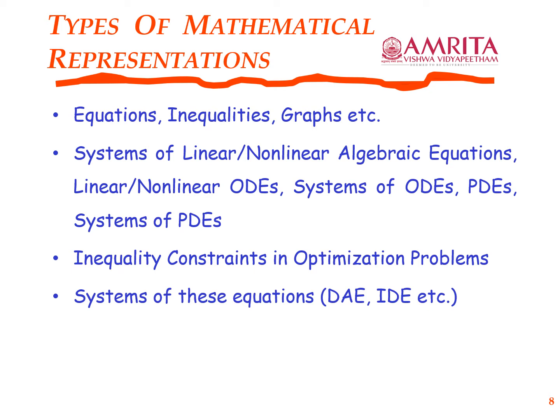That is, multiply that with the probability distribution, and then multiply it with your concentration of that particular fluid particle at the inlet, and then you integrate over various times from the inlet to outlet. So you get basically an integral equation for the exit concentration.